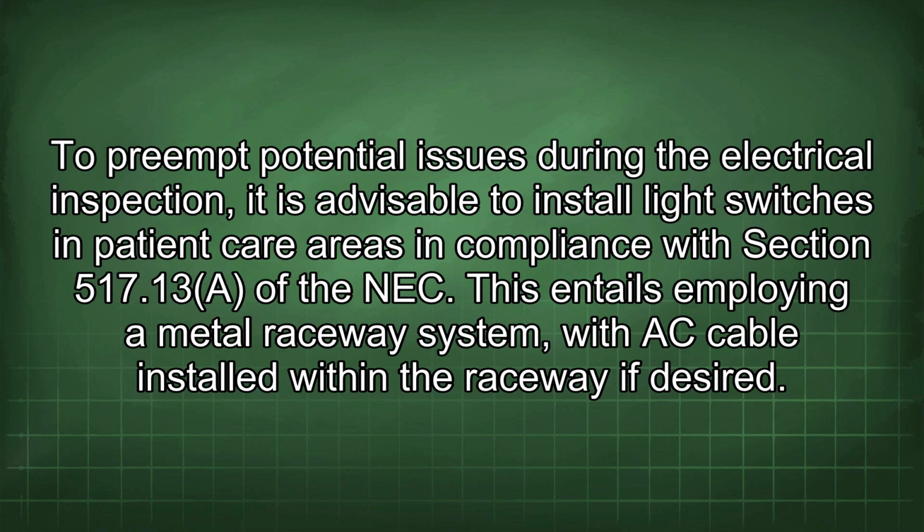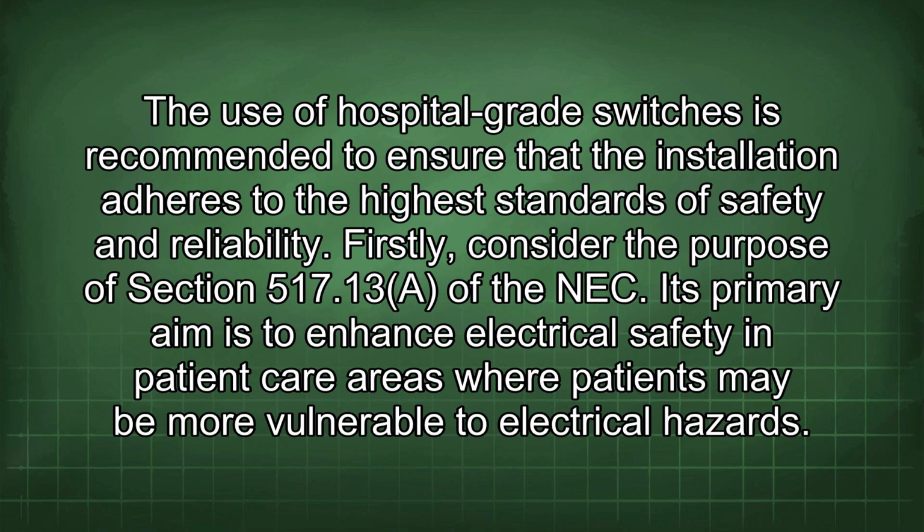To preempt potential issues during the electrical inspection, it is advisable to install light switches in patient care areas in compliance with Section 517.13 of the NEC. This entails employing a metal raceway system with AC cable installed within the raceway if desired. The use of hospital-grade switches is recommended to ensure that the installation adheres to the highest standards of safety and reliability.